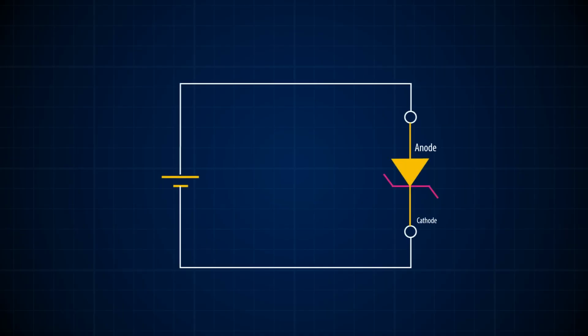The Zener diode, like regular diodes, consists of a silicon PN junction which, when biased in the forward direction, that is, when the anode has a higher potential than the cathode, allows current to pass through like a regular wire. When the voltage is reversed, or when the potential at the cathode is higher than the potential at the anode, the diode is said to be in reverse bias and will behave as an open circuit. A Zener diode in a similar configuration is specifically designed to conduct when the reverse voltage is greater than what we term as the breakdown voltage.